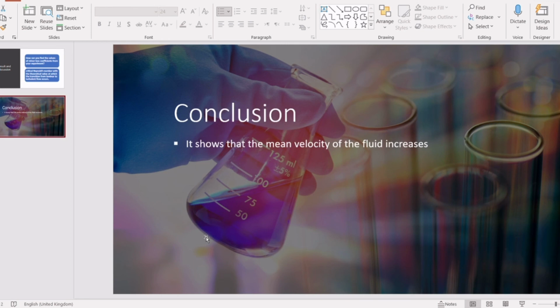Throughout this experiment, the experimental values for the major and minor head loss are calculated and compared to the theoretical values respectively. Major head loss is caused by the frictional force in the straight pipe, and minor head loss is caused by the loss coefficient of the various pipe fittings.